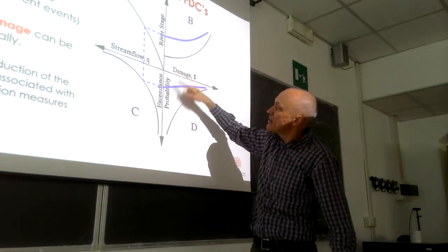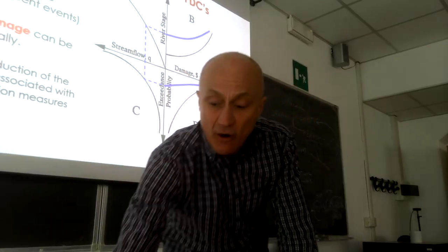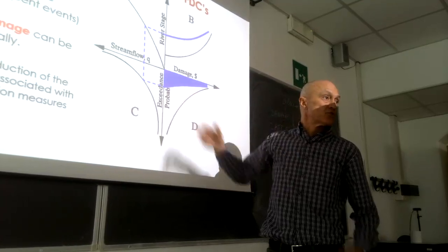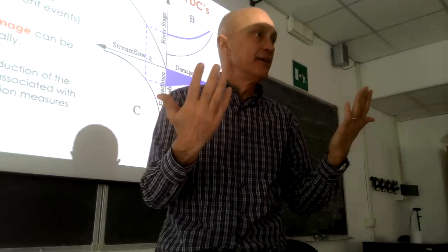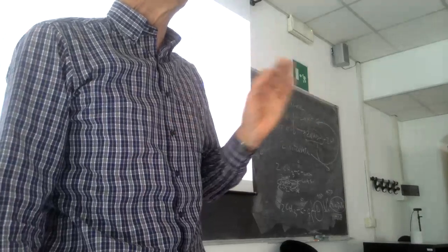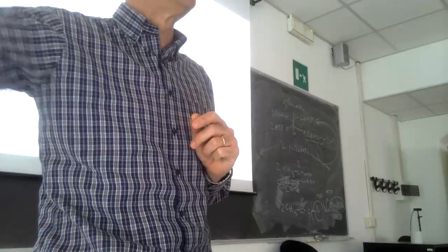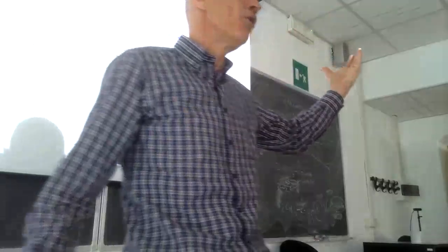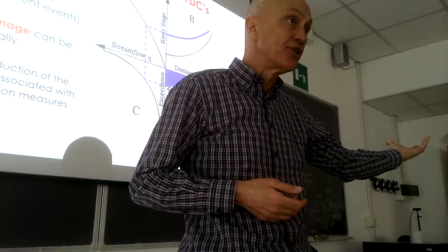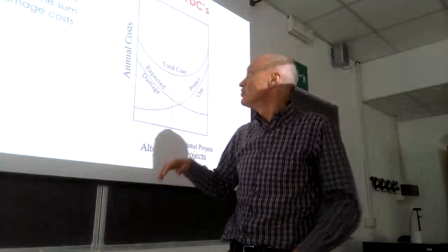Building a levee brings in some costs. A damage is a loss, a cost, but also constructing a defense structure has some cost. With this graphical approach, you can compare the expected damage as the height of the levee goes up, and then the cost of the levee as the height of the levee goes up.